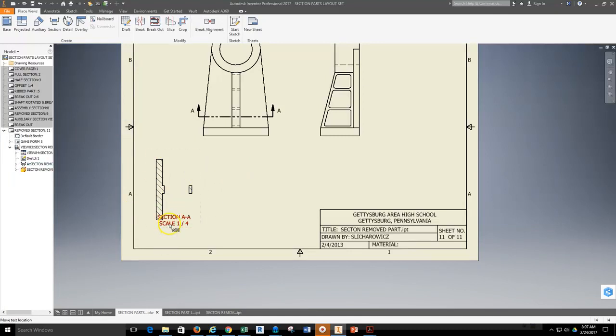and then I can start roughly positioning this where I would like to see it. Go ahead and grab my text and bring it off of my section view. So the next thing is now just positioning this particular cut plane so that it is in the proper orientation to the bottom of the part, or in this particular case, this is now the datum edge.